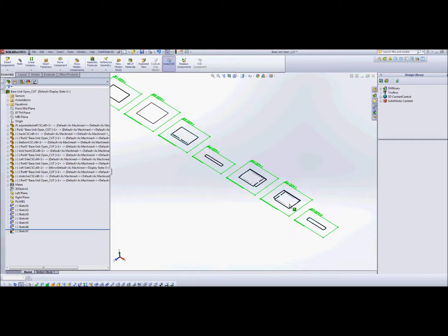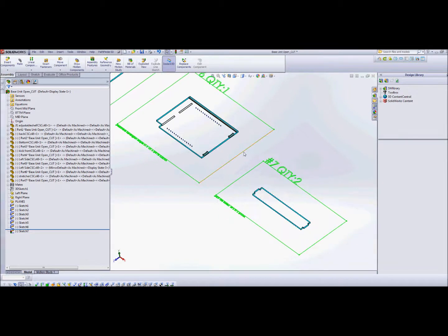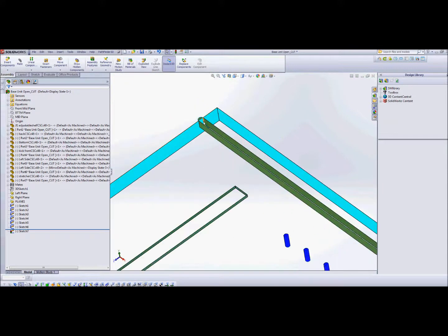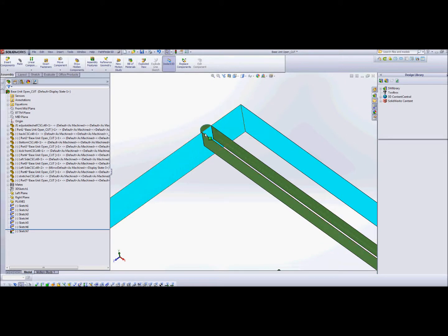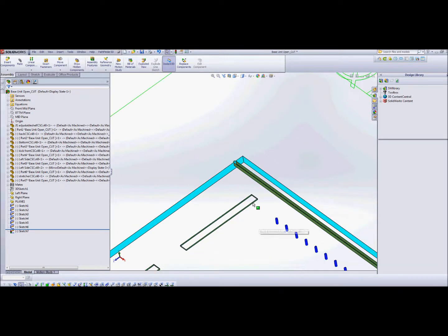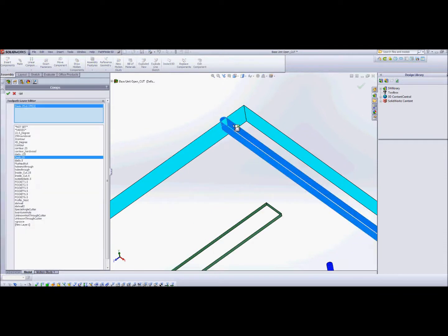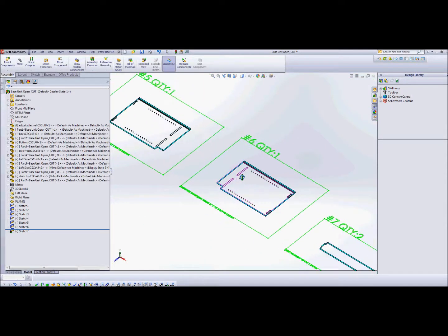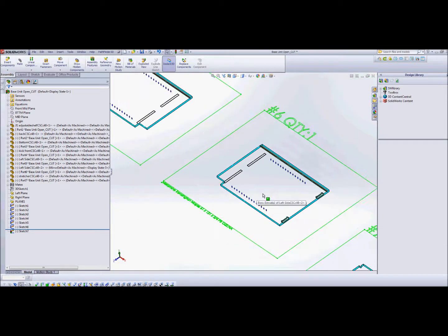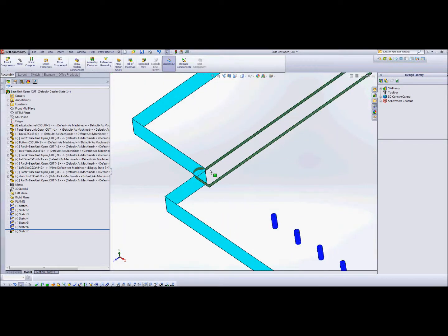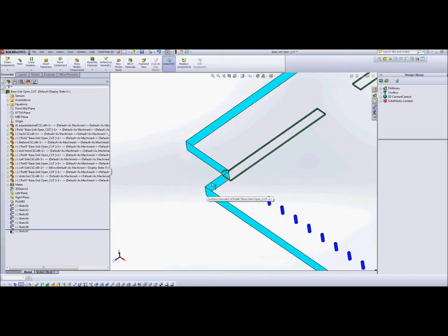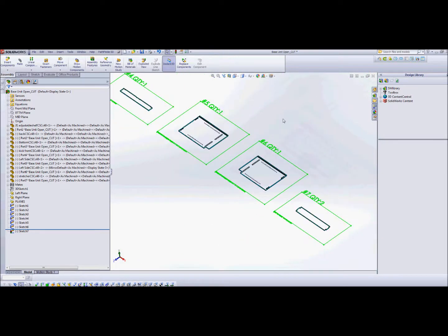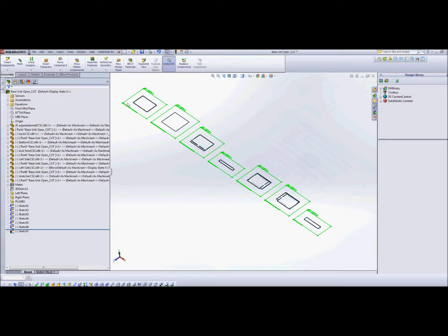So we now have a row of parts that are laid down in the assembly, and you'll notice that the dados have a loop to make sure they go all the way out the part, and they are layered, so I can click on it and make sure that's dado 2.25. Most parts it'll get automatically. There's a few custom things that it might not know what to do with, and you would have to manually go in there and create them. These are surfaces, and so they're easy to draw in SolidWorks and layer. So once you're satisfied with this, it would be a completely automatic assembly.